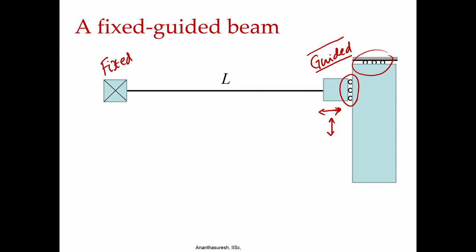That is what we will discuss now, because we discussed at length about the cantilever beam. Now, we move on to other boundary conditions. If you have a fixed guided beam, then it is going to deflect like this. The beam over there, when you apply this force, it is going to deform like this. In that process, it looks like here it is stretched because this length is more. That is because in this slide I have not shown the movement in the axial direction. So, we will see that properly.